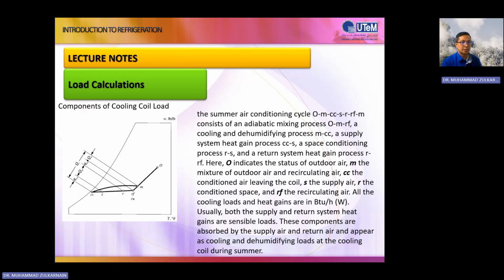So we collect the air to treat from the outside space, and then we contain it in one chamber we call the mixing chamber. Why do we call it mixing? This chamber mixes the return air and outside air, so that's why we call M a mixture.